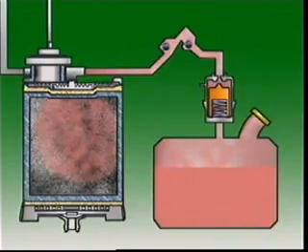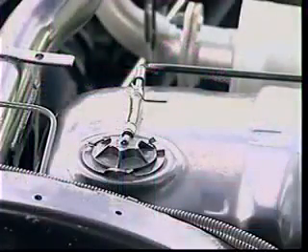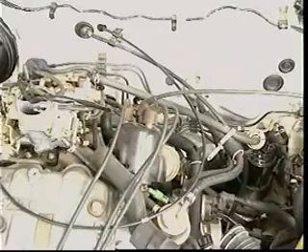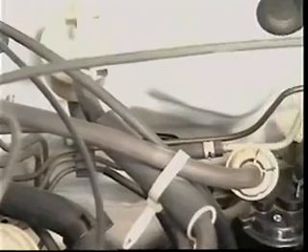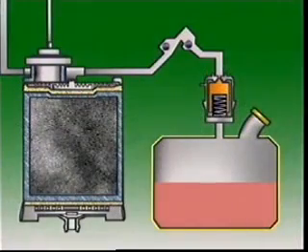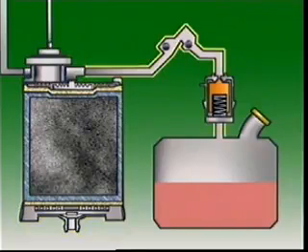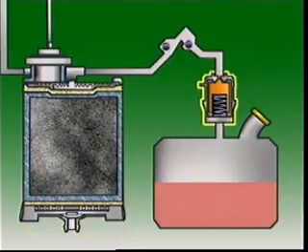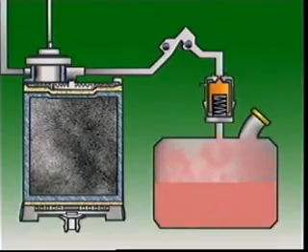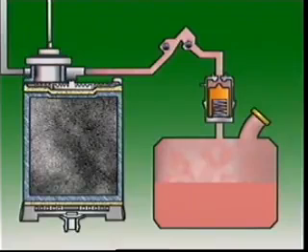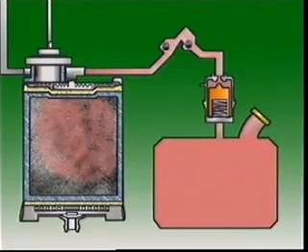Fuel expands and contracts as temperature rises and falls, so fuel tanks are vented to let them breathe. Modern emission controls prevent tanks being vented directly to the atmosphere. They must use evaporative control systems. Vapor from the fuel tank is trapped in a charcoal canister and stored there until it is burned in the engine. A vapor or vent line with a check valve connects the space above the liquid fuel with the canister. This valve opens when pressure starts to rise and lets vapor through, but not liquid. Liquid fuel closes the check valve and blocks the line, stopping liquid fuel reaching the charcoal.